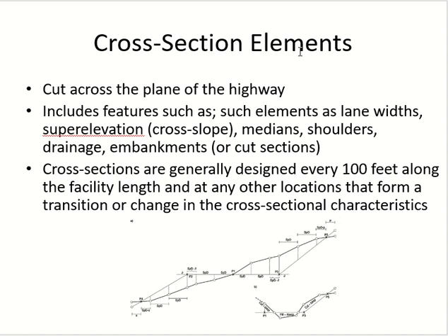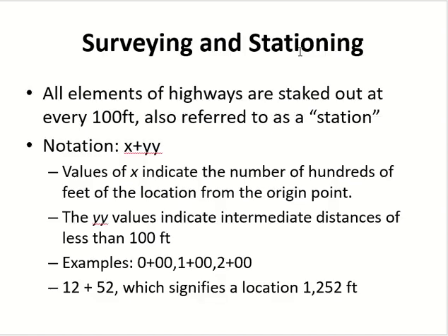So you will not wait, you will not give the drawing for the next cross section which is after 100 feet. No, you have to give the cross section drawing where the cross section is changing. This is mandatory, right? Otherwise he will miss the change. Clear? Okay, so normal practice is cross section every 100 feet. Otherwise, wherever the change happens, you have to provide the cross section.